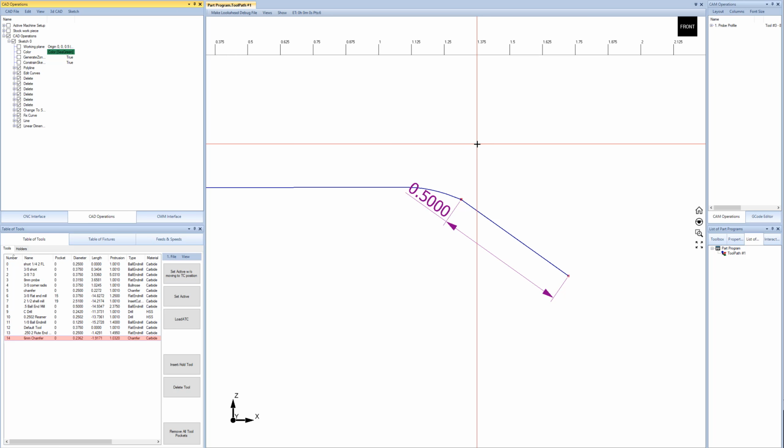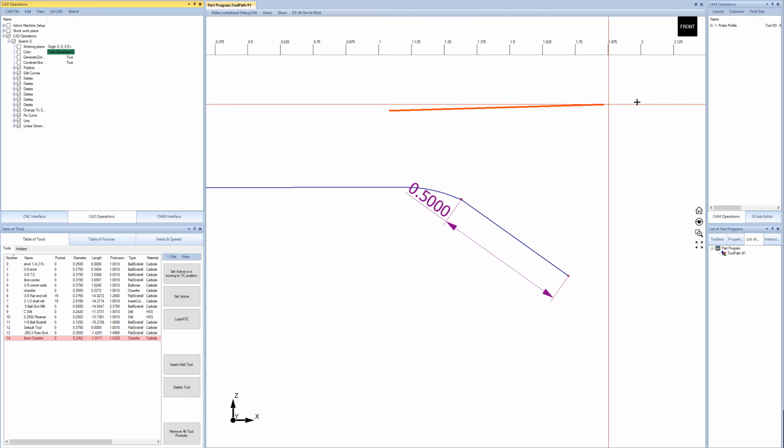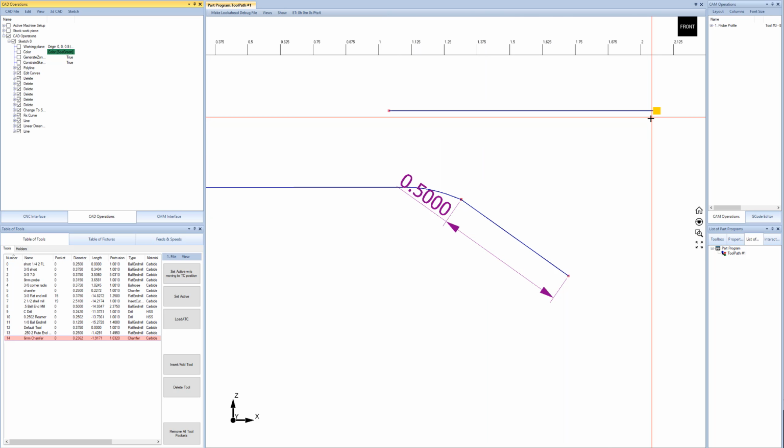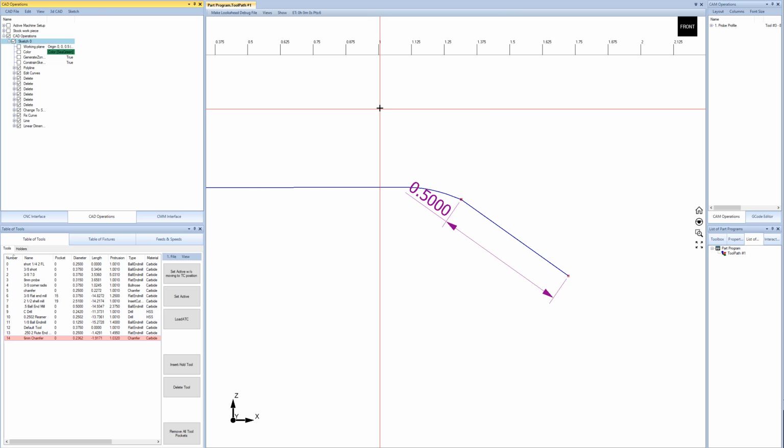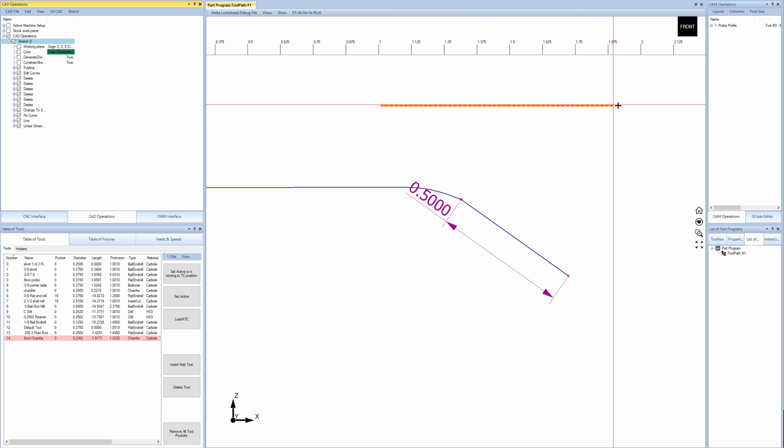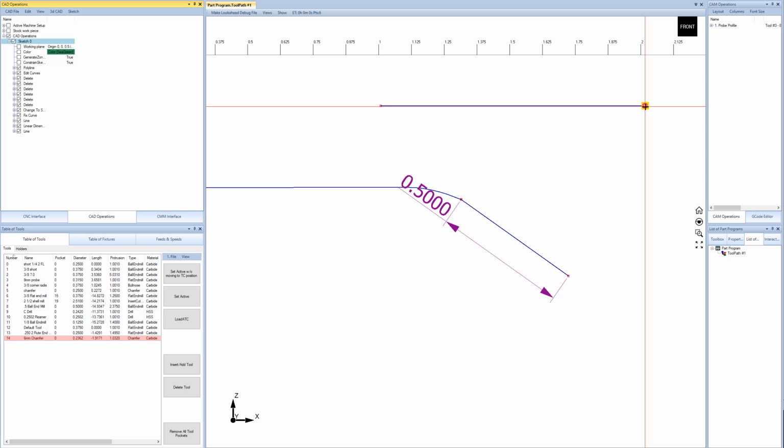So now I'm going to adjust the angle of this. I'm going to create a line. Now this line is not really important. This is considered to be a construction line. This is going to be used as a horizontal reference to this. And I know this is always going to remain horizontal because when I drew it, let's draw it again. I'll delete the line. When I hit L and then draw the line, you can see that yellow dotted line there. That means that it's always going to be relative to the horizontal axis, to the x-axis.